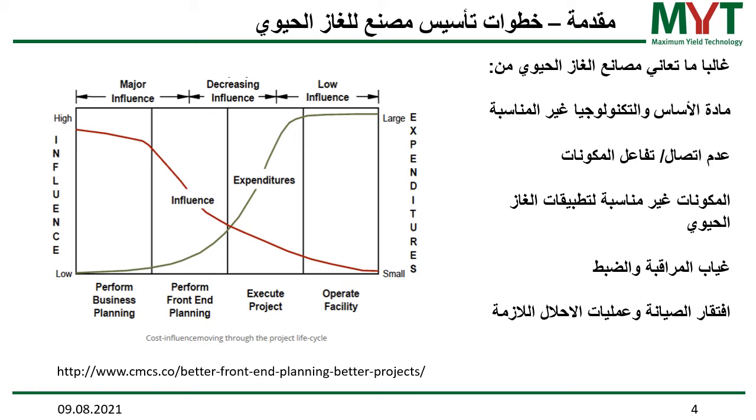You don't have an H2S measurement in your gas analyzing system, and all of a sudden your CHP breaks down due to corrosion. And this is an example of lack of monitoring and control. With a simple sensor for H2S in the gas analyzer, you would be able to recognize and identify the problem, and go on with some measures against it.